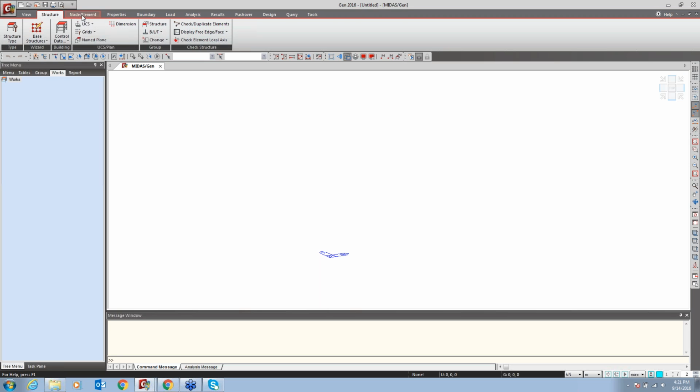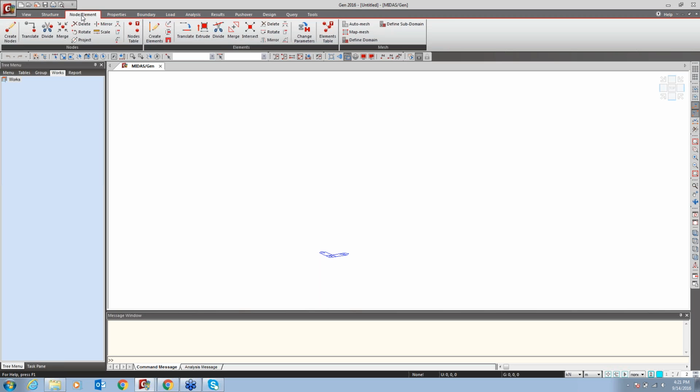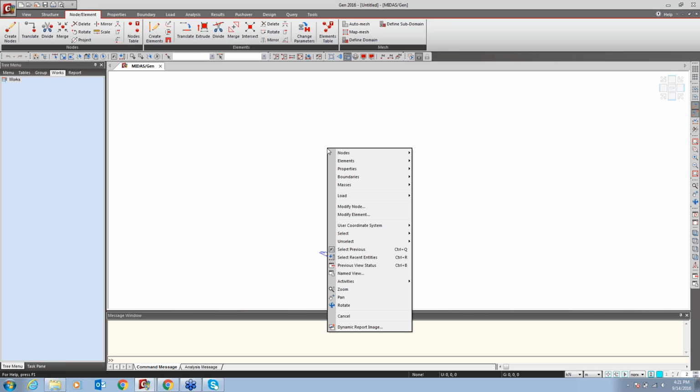And the last method is about the nodes and elements, meaning you can directly start with the nodes. Where you want the column points, over there first you start with the nodes. I will show you how we can use the nodes and element option. I just come to this option, nodes and element, say create node, or else you can right click on the screen also. Before run analysis, right click is model oriented, and after run analysis, right click is for result oriented.